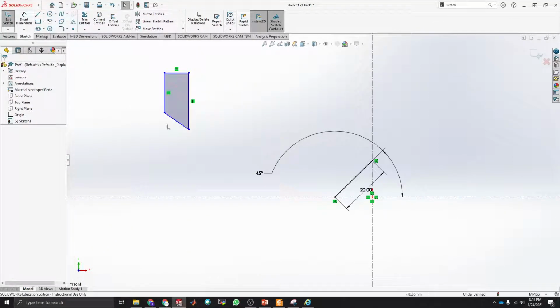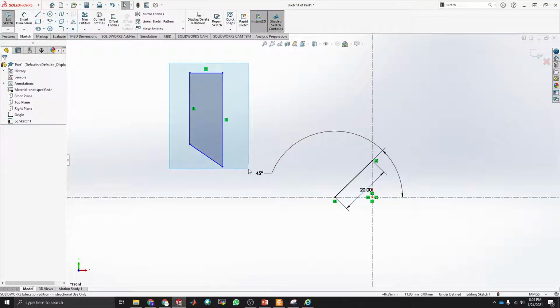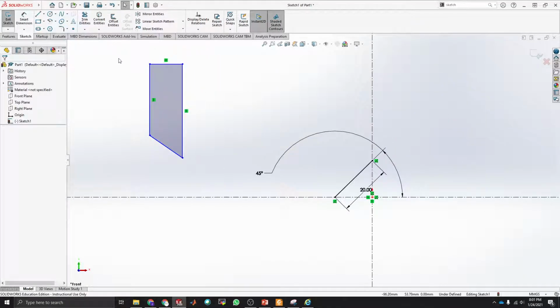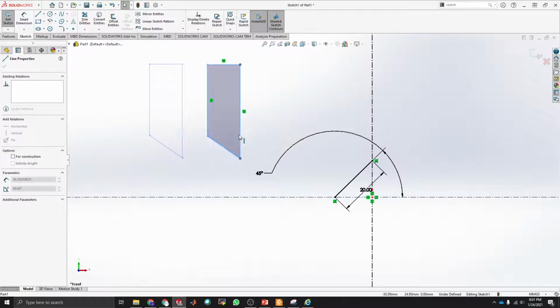So in this case, I created this geometry, and once the geometry is closed, we will see that the closed area would be in a dark gray color. Again, since none of these points are actually defined, they are free in the space, I can move them around, or I can just move everything together. Now to select everything, I just use the left click in the mouse and close everything inside of the selection box, and then I can move everything.